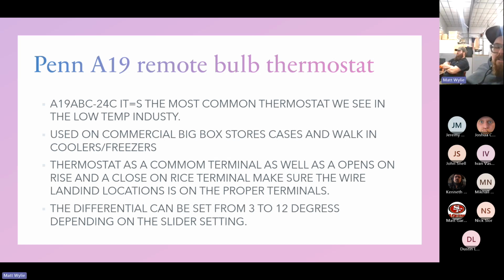On the side of the pen thermostats, there's that differential switch. I always leave it alone, never touch it. But they can be set between 3 and 12 degrees by just sliding it up and down.